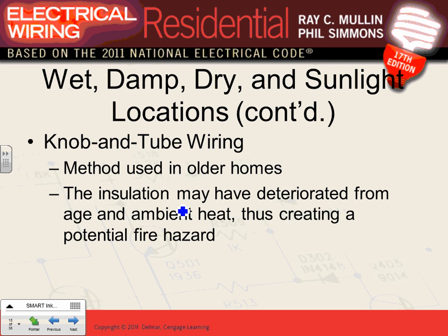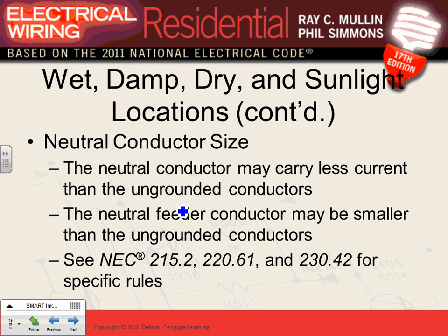We're not electricians, but the problem with knob and tube guys is they tap them and share the neutral. If you're in a situation where you have to have arc fault circuit interrupters, the neutral is shared, or the GFCIs are shared, and they keep tripping. And of course, when they tap without the junction box, for most applications that's a violation of the code. Every time you tap or terminate a conductor, we have to have a junction box.